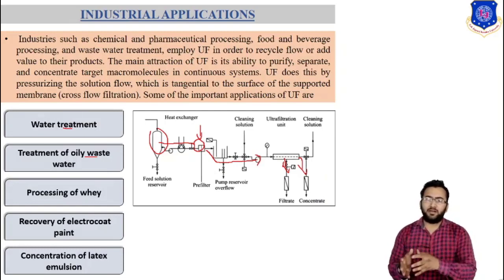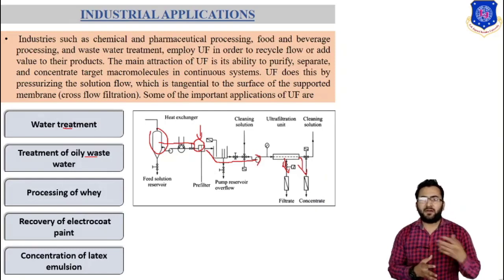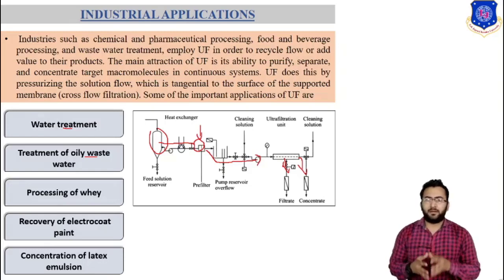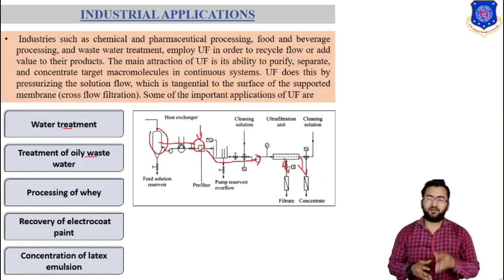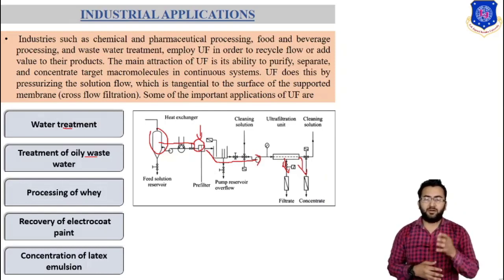The membrane retains the stable emulsified oil, while the water and a very low concentration of dissolved oil and free surfactant pass through the membrane. It can be concentrated up to 10% and we can reuse it. Oil in water emulsion containing 10% oil is used as lubricating and cooling fluid for a process involving single metal sheet. After the process, excess oil emulsion is removed from the can in three stages, with a 60 degrees Celsius water washing cycle, then the rinsing water of a simple production line accumulates about 5 cubic meters per day and contains about 0.6 gram per liter of oil.